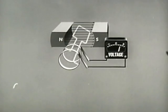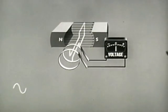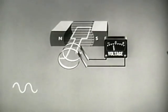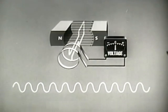This use of slip rings is the only structural difference between AC and DC generators. One complete revolution of the armature will produce one cycle of alternating voltage. If the armature rotates once each second, the frequency of the alternating electromotive force or voltage is 1 cycle per second. 10 mechanical revolutions of the armature per second produce a frequency of 10 cycles per second. Frequency, or the number of cycles per period of time, is directly related to the rotating speed.